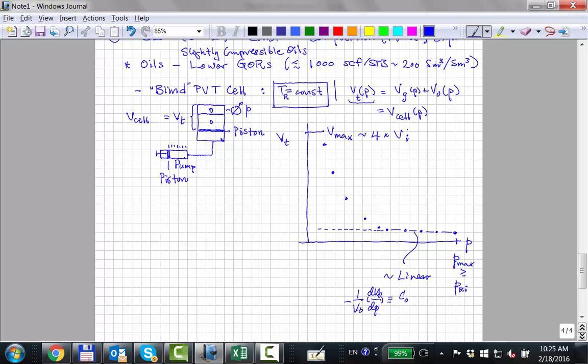And so what we're looking for is this discontinuity. We've got this very nonlinear, highly increasing trend, and it's due to the gas, basically this trend here, and where it intersects this linear trend here, that's going to be approximately the best we can come up with for the bubble point. That'll be the bubble point pressure. So below that pressure, we get a little bit of gas coming out of solution. Its compressibility is probably 10 times at least the oil compressibility, so that 1 psi pressure drop gives a lot more volume increase than if it was just an oil. Okay?